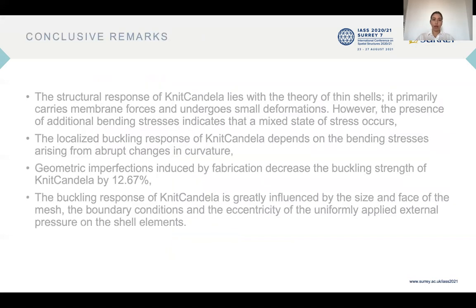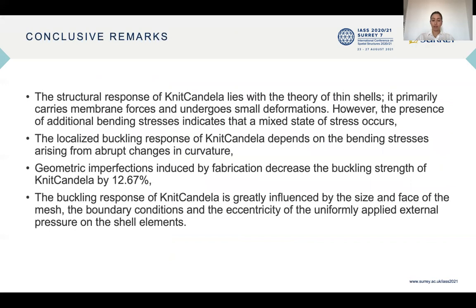The main concluding remarks of this research study are the following. KnitCandela lies within the theory of thin shells. Additionally, the localized buckling response of KnitCandela depends on the bending stresses arising from abrupt changes in curvature. Geometric imperfections also influence the buckling strength of KnitCandela. But also, the buckling response of KnitCandela is greatly influenced by the size and shape of the mesh and the boundary conditions.